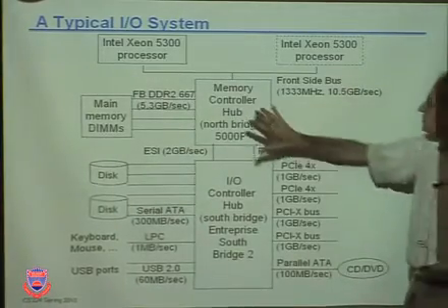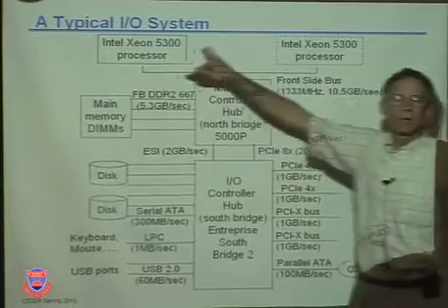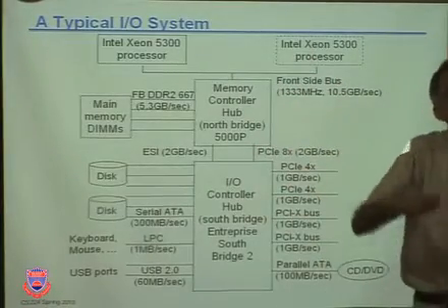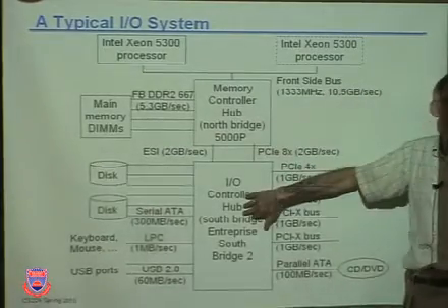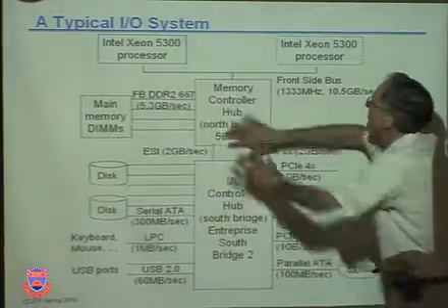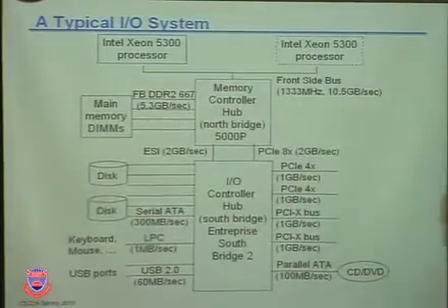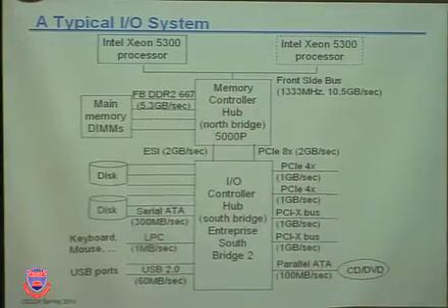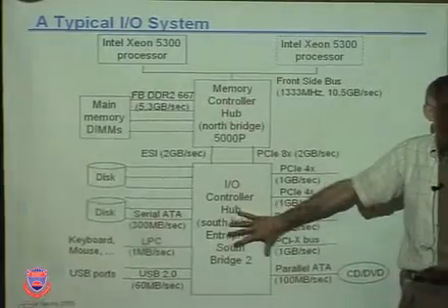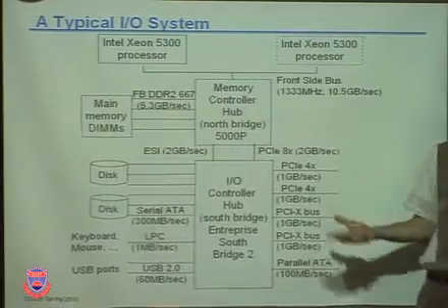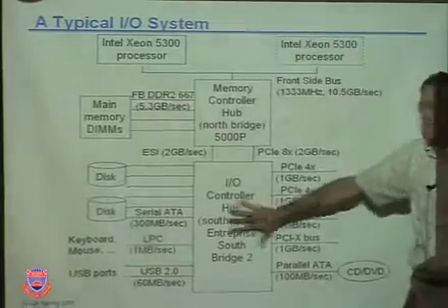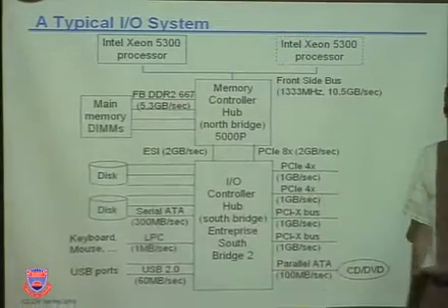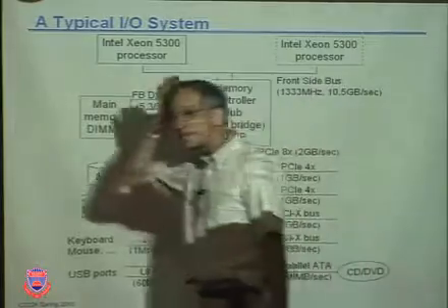Now, it turns out these memory controllers, because of such large amount of available transistors on the chips, are becoming integrated into the chips. So instead of a chipset with 1, 2, now we can go down to 1 because this is starting to migrate into the processor, leaving us only a single I/O controller chip. Understand? Okay, so what we've got is you need a processor chip. In the old architecture, you need a north bridge and a south bridge, and you've just finished your system configuration. You need a motherboard to connect everything together. In newer architectures, you need a processor chip, and you need your I/O controller chip, and they're done, plus your motherboard to connect everything. This is pretty basic system architecture.